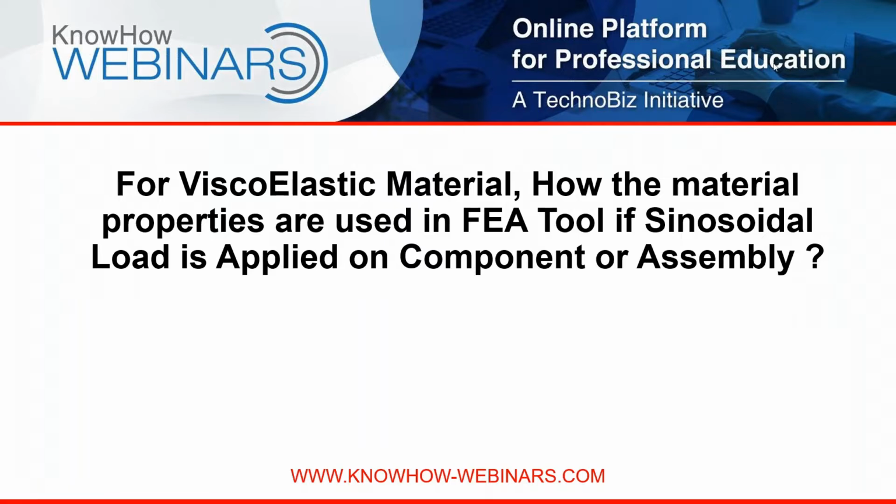For a viscoelastic material, how are the material properties used in an FEA tool if a sinusoidal load is applied on the component or assembly? So the question is, what material properties are used in the FEA tool if a sinusoidal load is applied on a component or assembly. In FEA software, there are probably 3 ways by which you can input the material properties.